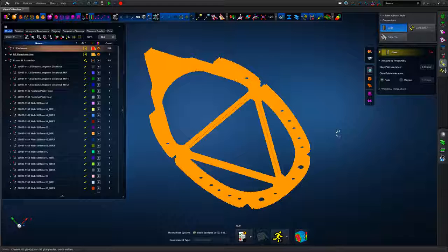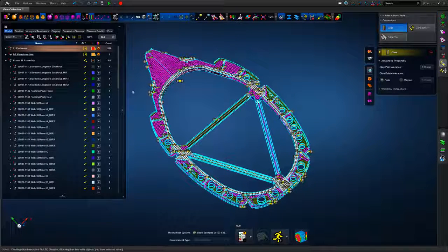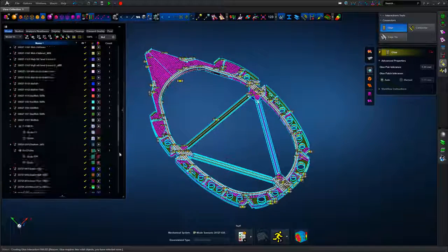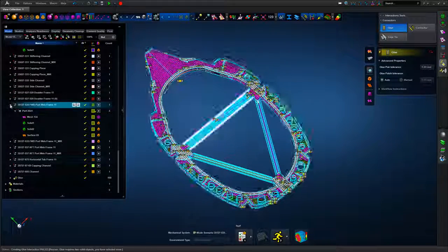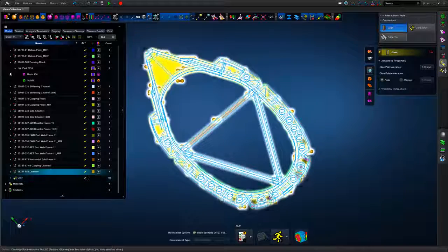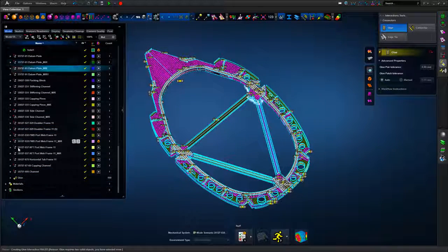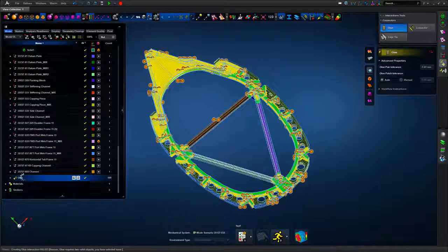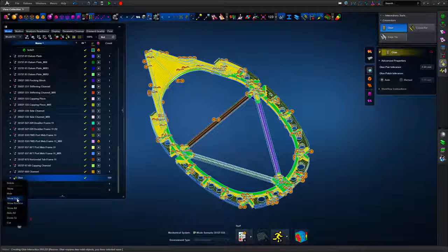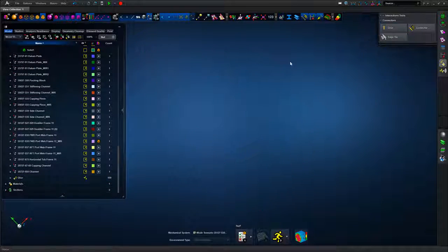Using the default glue pair tolerance of 5mm, it looks for entities within that tolerance and glues them together. You may well have seen one of the previous tutorials or webinars where we looked at explicit connector technology, and part of that was focused on the glue, which is effectively an internal MPC definition defined on an MSC Nastran base level.